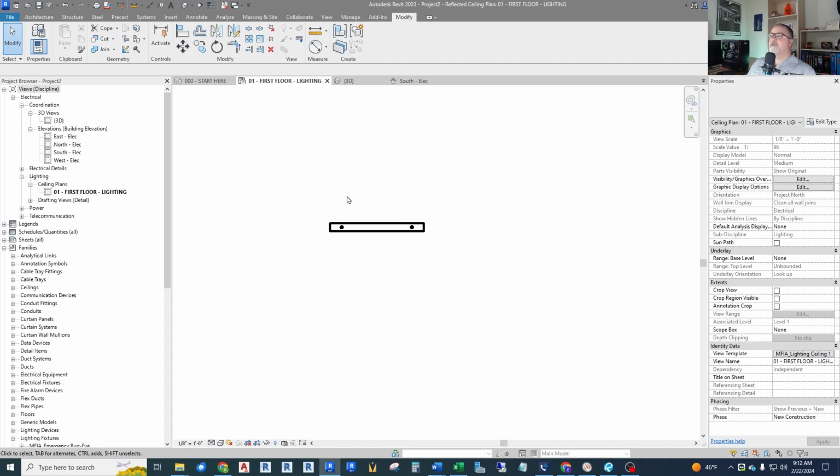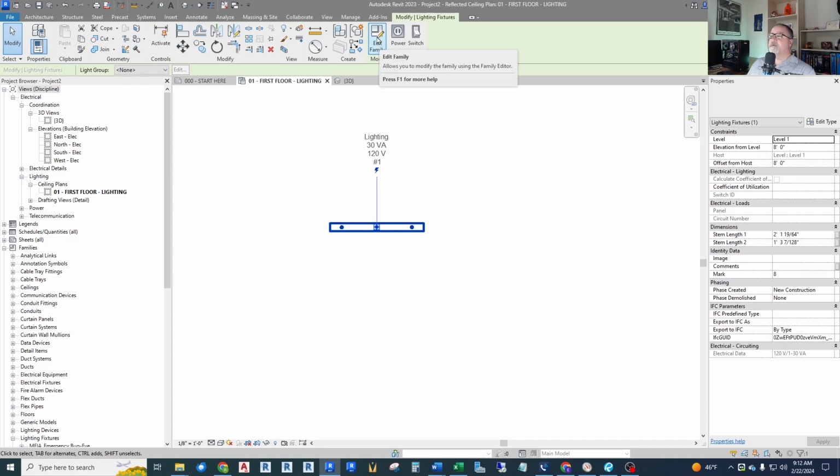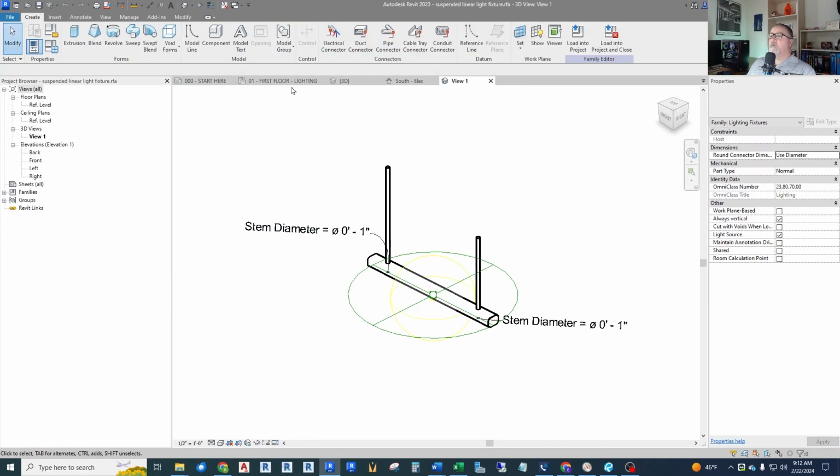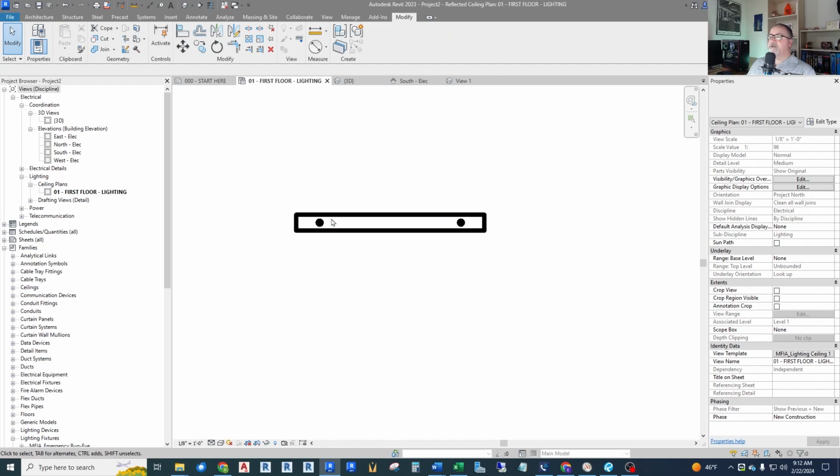Let's go further on. One more thing I want to do here is deal with the emergency symbol. We like to use a filled-in circle or a filled-in light fixture or something to indicate that this fixture is attached to or contains some kind of a backup element. It may have a battery backup in it, or it may be attached to a generator or inverter circuit, something that clearly indicates that it is an emergency light fixture. So what I need to do is create an annotative symbol. Annotative means that no matter what scale my finished plan is in, the symbol will be the same size. It'll be an 1/8-inch circle, no matter what scale my drawing's at.